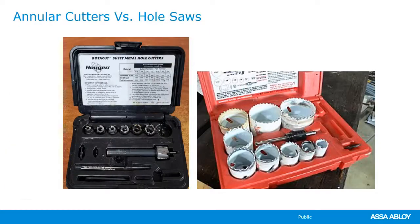Sometimes we have to drill larger holes, and it could be because it's a spindle hole that goes all the way through the door from an exit device trim. It could be a mortise lock, a mortise cylinder hole that goes through either one side or both sides of the door.